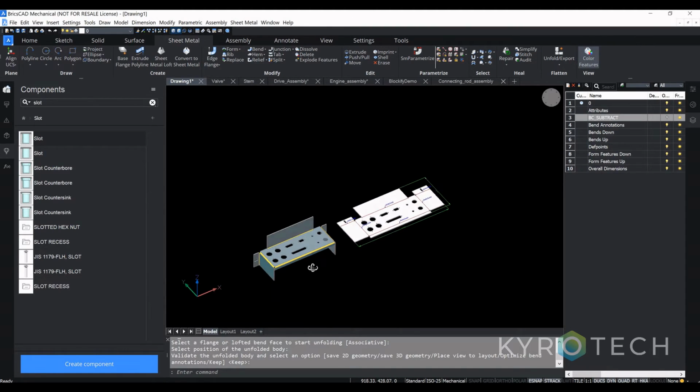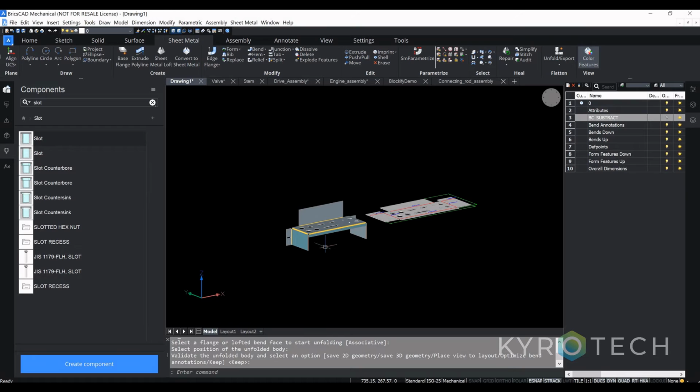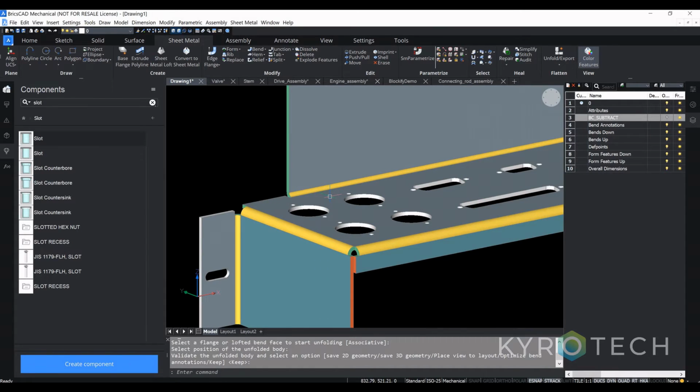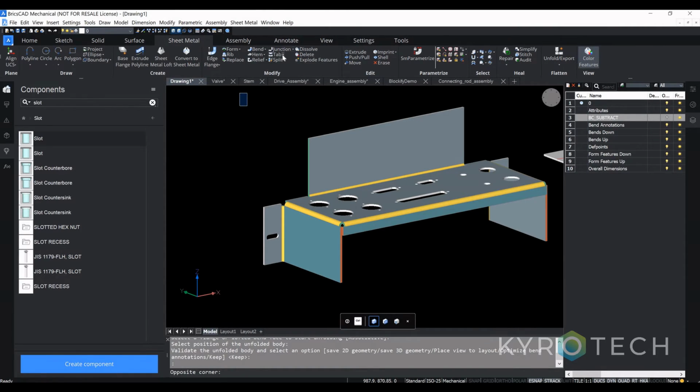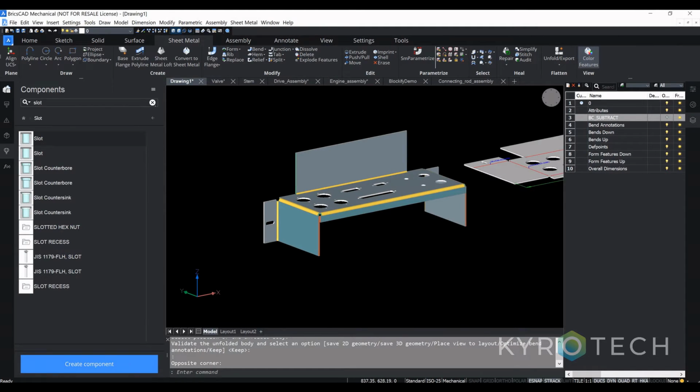Now this we did from scratch. Again, we can shift your solid models into sheet metal by converting into sheet metal and then using the shell command, and automatically BricsCAD will identify all the bends and all the flanges and allocate them accordingly, all the junctions also. Along with that, we also have the hem facility, the bend facilities, and junction types, and the tabs also. We can create tabs too in BricsCAD sheet metal. Now, moving on, we will see a few other additional features.